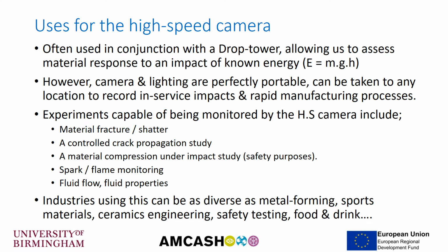The industrial uses for a high-speed camera can be wide-ranging. Often we use it in conjunction with the drop tower that we have at the university, which allows us to assess the material response to an impact of a known energy. However, our camera and our lighting are perfectly portable, so we can take them to any locations to record in-service impacts and rapid manufacturing processes at various factories, workshops or test centres.